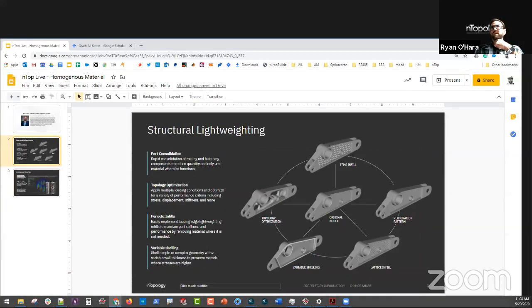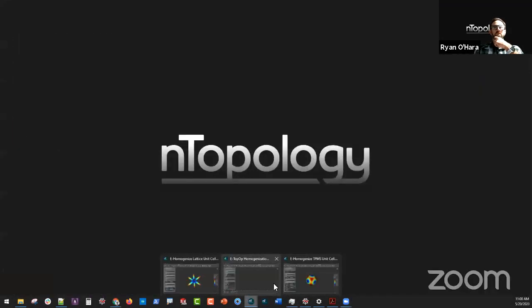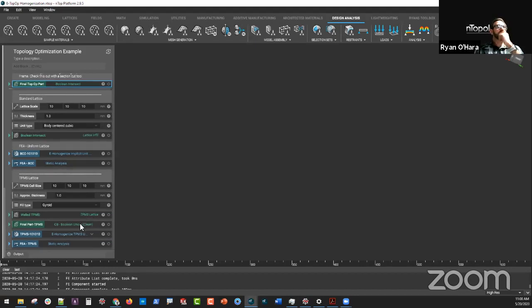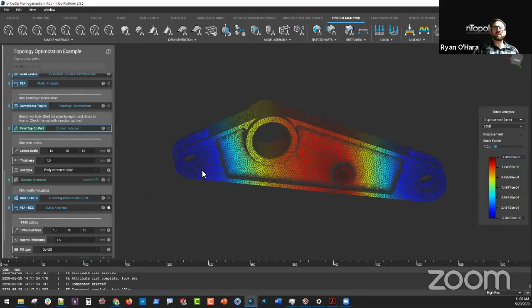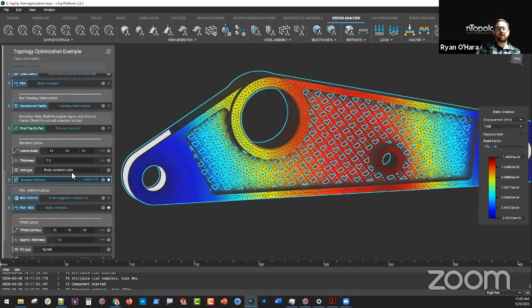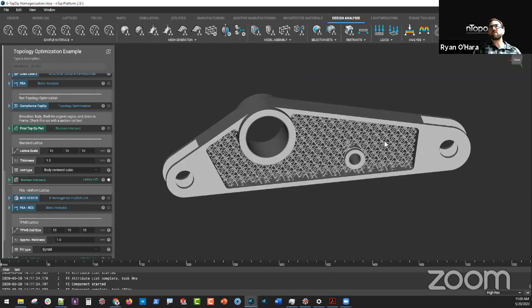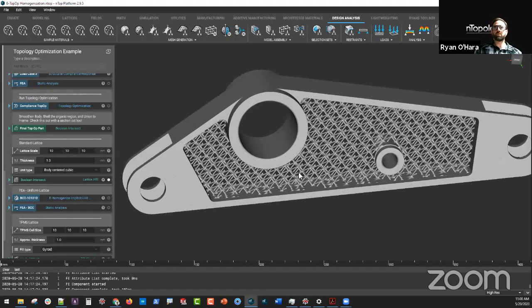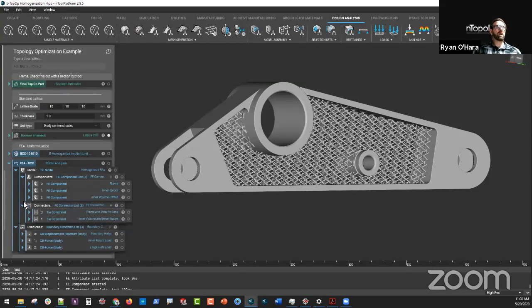we've provided a number of different infills here, and so we're just going to recreate some of those in this scenario. So let's go back. And so to set this up, we had to do something slightly different in that we know we have an area that we want to analyze. In this case, we're going to treat this webbing, even though we want this to have a lattice like this guy, we don't necessarily want to do all the simulation on each individual lattice. This could be a huge matrix and could be very, very difficult to solve, especially when you're doing design exploration. So an easier way to do that is to actually set up a new model.